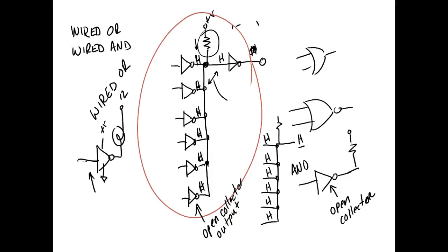without damage. If they've got totem pole outputs and you connect them together, they might work for a while, but sooner or later that little sinking transistor is going to give up the ghost, right? You understand why? Because it can't handle those short circuit outputs. So we can get quite a bit of current out of a gate, but it no longer gives us 2.4 volts. So as soon as you get above the rated output, the maximum output current, then the output's going to start dropping down.